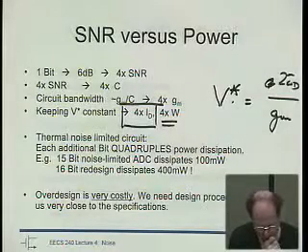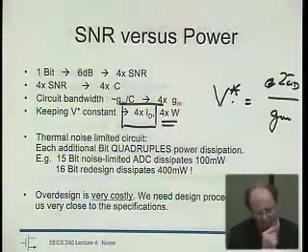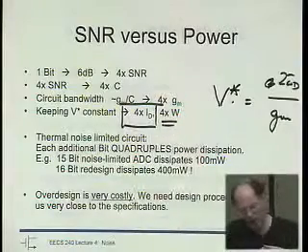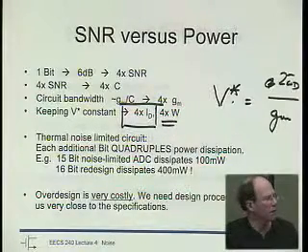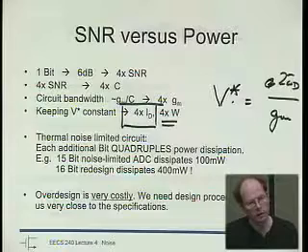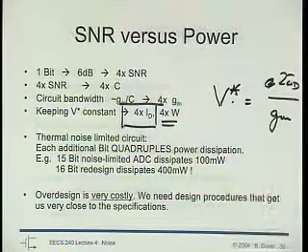No, the signal didn't increase. The idea is only that we need to generate enough gm, right? The signal power was simply limited by the supply voltage. It was VDD squared times some factor. So increasing the current that we drain from the supply hasn't increased our signal power.